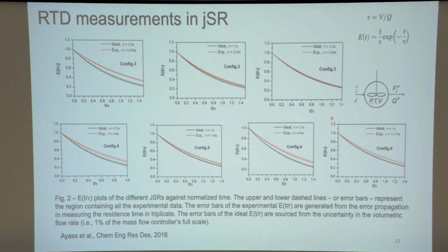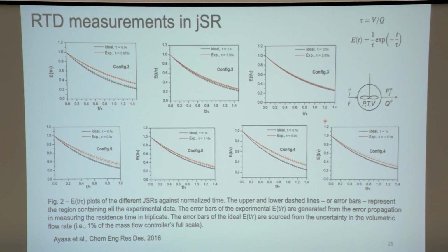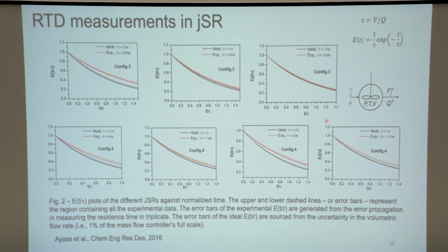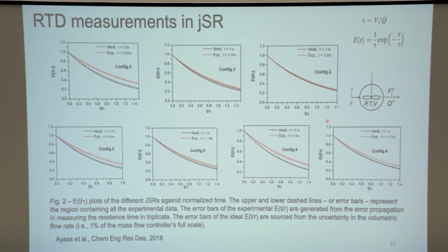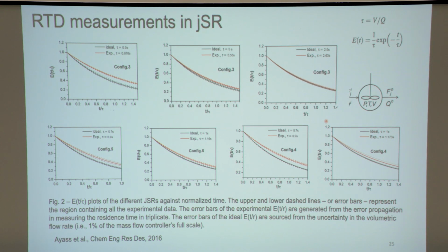If the reactant gases are coming in too slowly, then it won't be well mixed. The gases will get in there, there will be diffusion, there will be gradients, and then they'll leave the reactor. Then it's not well mixed. If it's too fast, you can have too much collision against the walls and some turbulent mixing, and then you don't get the exact homogeneous mixture inside of the reactor.